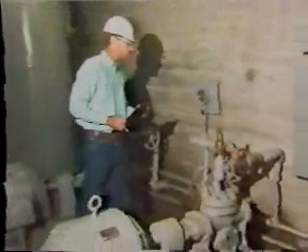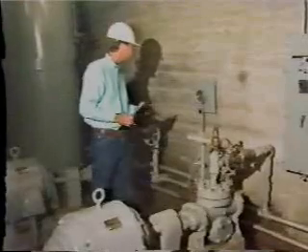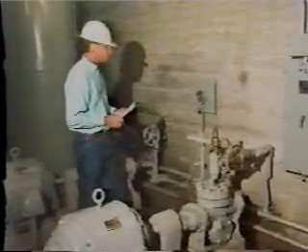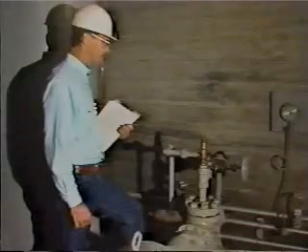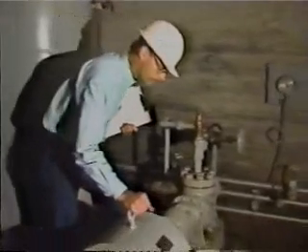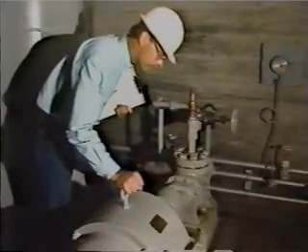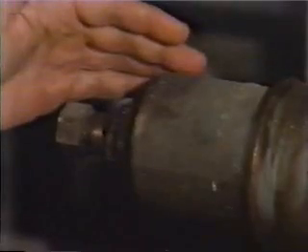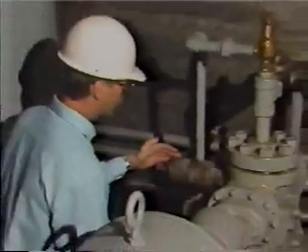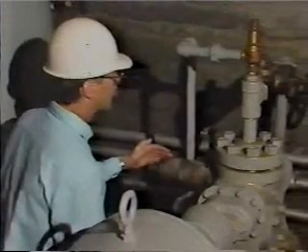As the gate begins to rise, look at the operating pressure to ensure that the system isn't using more pressure than usual to raise the gate. Watch for signs of a malfunction, such as binding. Also watch the actuator to see if scratches are revealed as it moves. And listen for unusual noises. After the gate is fully opened, check the pressure relief valve, or pressure switch setting, to make sure the system stops when it should.